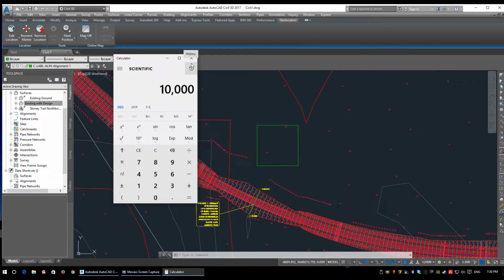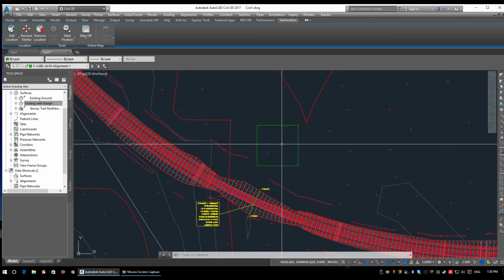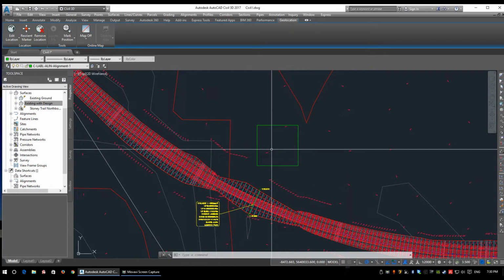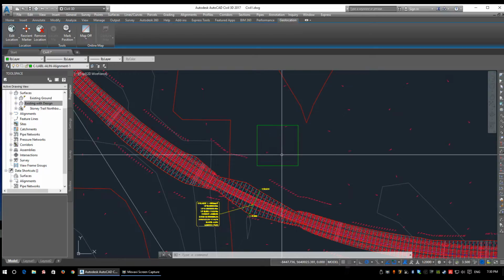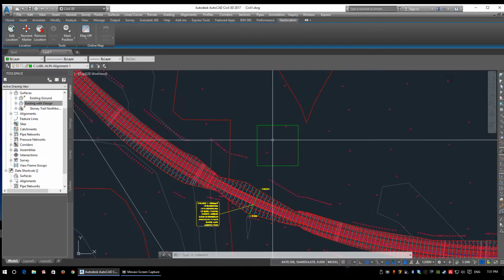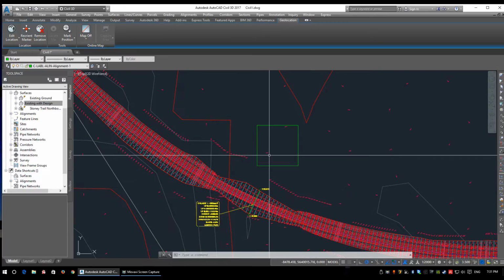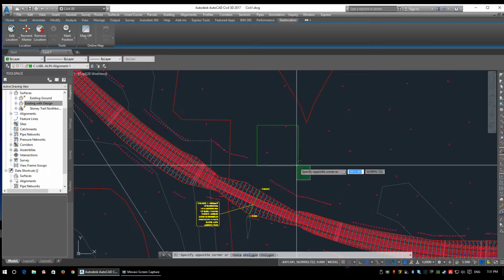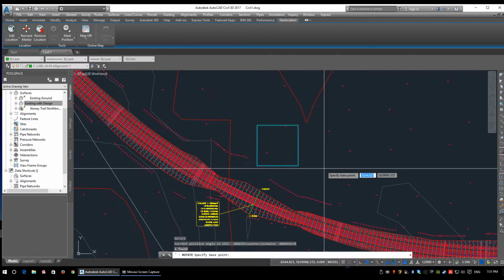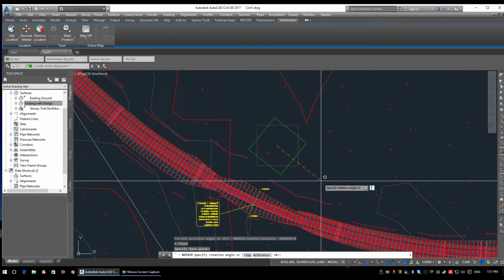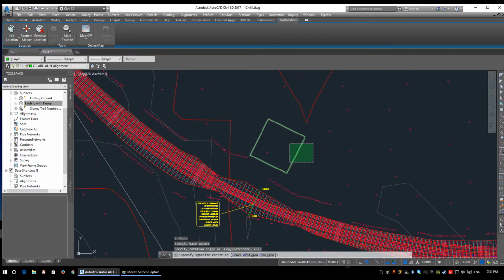Now, we can make it smaller if we make it deeper. So if we go 2 meters deep, we could probably make it 5,000 square meters. So 100 by 50. So it all depends on the land. It depends where you're designing it. It depends on groundwater underneath and everything. So depending where the pond is, where the site is, that's what's going to constrain you. But for this exercise, we're just going to make a pond that's 100 by 100. And we're going to make it around 1 meter deep. We may have to go slightly more than 1 meter deep.